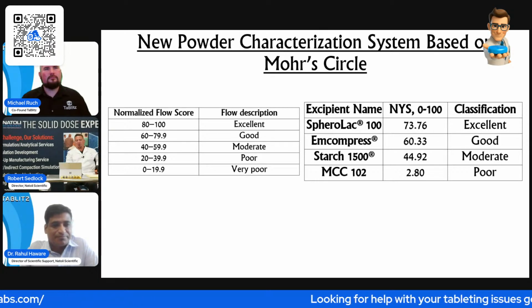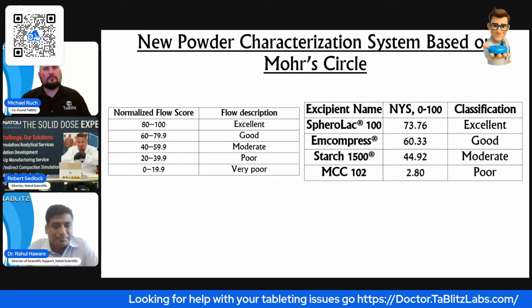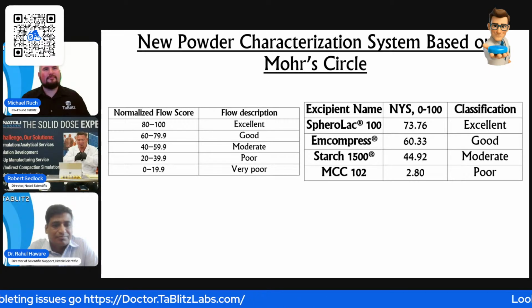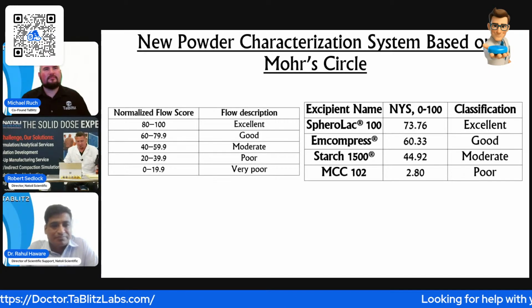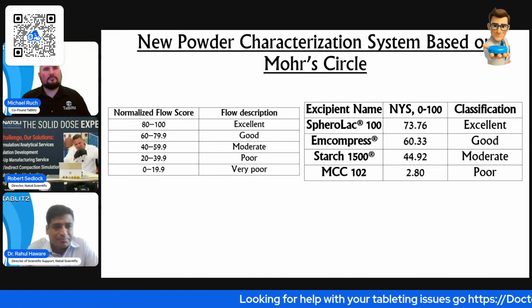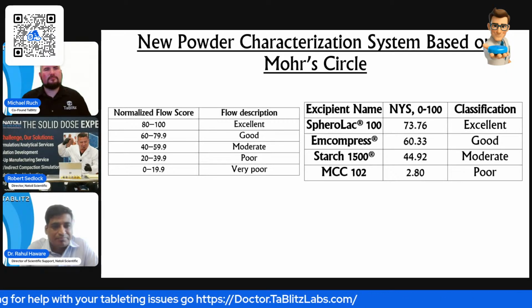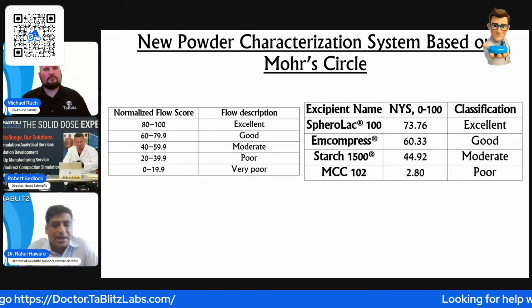So you need some cohesiveness when you're compacting and creating bonding of the particle-particle interaction, which kind of segues us to another topic here about sticking. Where does sticking come from, right? When you're compressing and compacting your powders, you want your particles to bond to each other. If they don't bond to each other, they're sticking to your punch face. Now that's the relationship between cohesion and adhesion, right, Rahul? Absolutely.